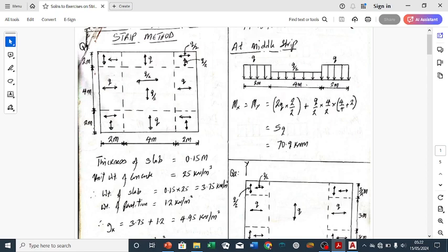So what we do next is to divide this whole slab into 2. Because if you divide it into 2, half of it will rotate at this end and half of it will rotate at this end. So if we calculate what happens at each end, then we are done. We will be able to get the moment we are looking for. So if we divide this into 2, imagine what we will have. This Q here will still be Q, and this distance will still be 2 meter.